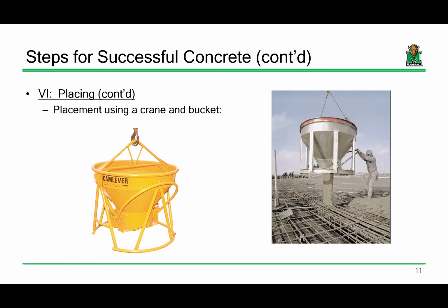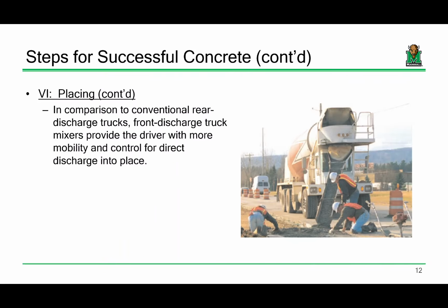But essentially what you would do is fill this up with concrete, transport it to where it needs to go, and then this handle, you just whoop, and it drops down. Again, you want to make sure that you're limiting your drop height to around 3 feet or so. You can also just place concrete out of the back of the truck.